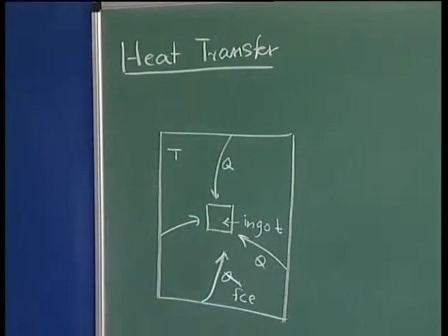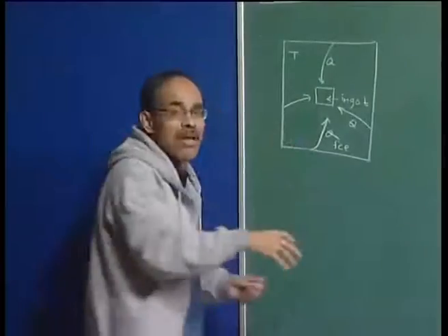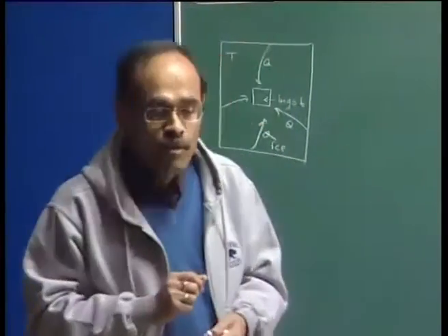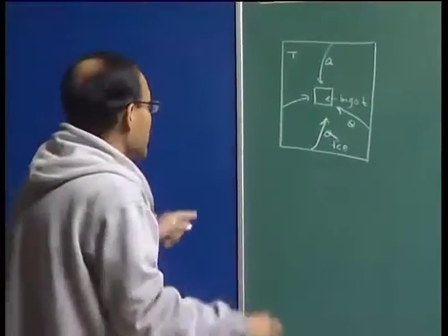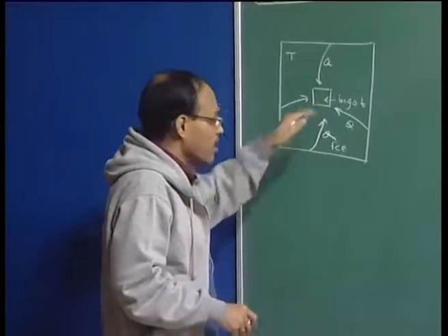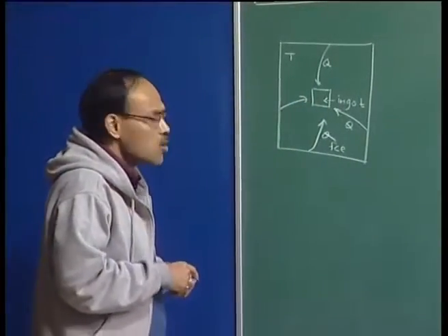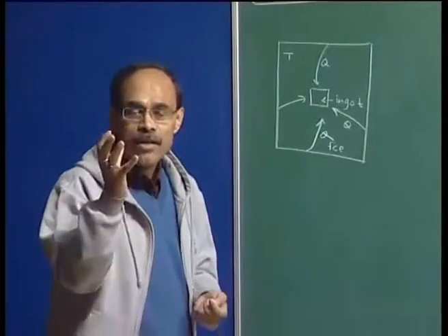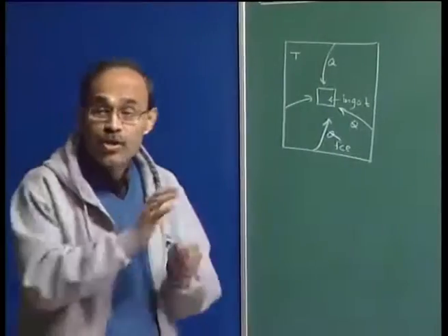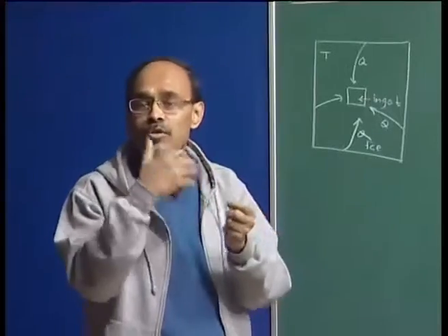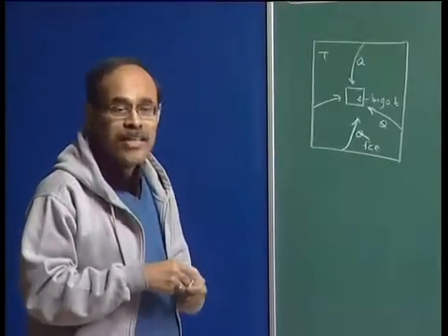Unless we know the fundamentals of heat flow within the furnace itself, from the furnace environment to the solid surface, and then within the solid, we will not be able to calculate the optimum reheating time, which essentially gives a constant ingot temperature at the end of the cycle. So, innumerable examples can be given where heat transfer plays a decisive role. There is no doubt that we will need a good background in heat transfer in order to tackle the efficiency of many metallurgical processes.